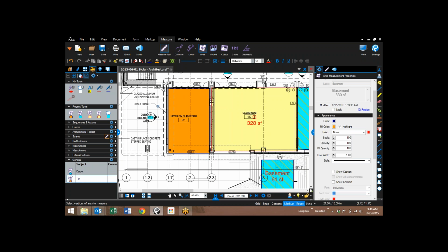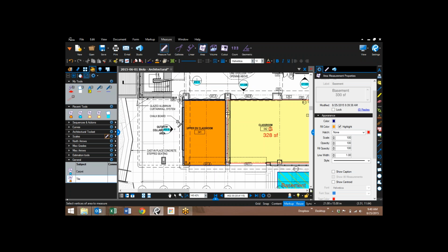So I'll do it one more time. The point here is to be able to make a square or rectangle in just one click rather than clicking each corner. So if I am on my tile mode, I click once and hold down on my one corner, and then I drag down, and then in order to make it a rectangle, I have to hold down Shift. I'm still holding down my first click, and I'm holding down Shift at the same time, and then I let go of my click, and then it makes it so I can make a rectangle.